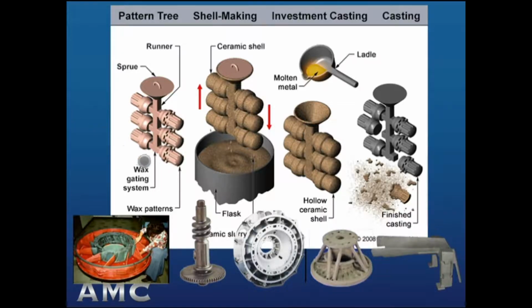Our next video is for the ceramic shell investment process, and it's a more complicated process, so we'll take this diagram of how the process works to give you a preview so that you can understand the video a little bit better. At the left side, we see wax patterns assembled on a tree. The wax patterns have the shape of the ultimate casting, which in this case there are 6 of them. And then those wax patterns are invested in a pre-ceramic powder along with a liquid pre-ceramic binder system to create a buildup of a shell around the wax patterns.